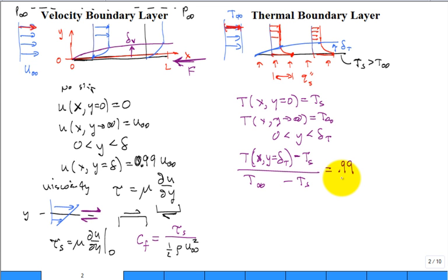And if you plot, they call this a theta. Let me quickly sketch it here. Don't want to sketch too many of these, but if I plot theta, here's that growth of that boundary layer. Theta is going to start at 0 and go to 1. Far away, theta is equal to 1.